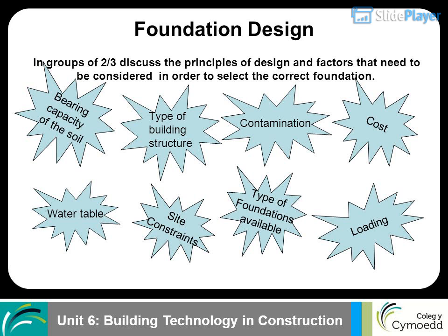Type of foundation. The type of building structure, how heavy the loads are that the building will carry or exert on the ground. The soil conditions, including whether the site is located in an area that has known problems such as radon gas, minerals or evidence of mineral extraction in the area. Options available, whether the foundations are suitable for the type of building that is being designed.